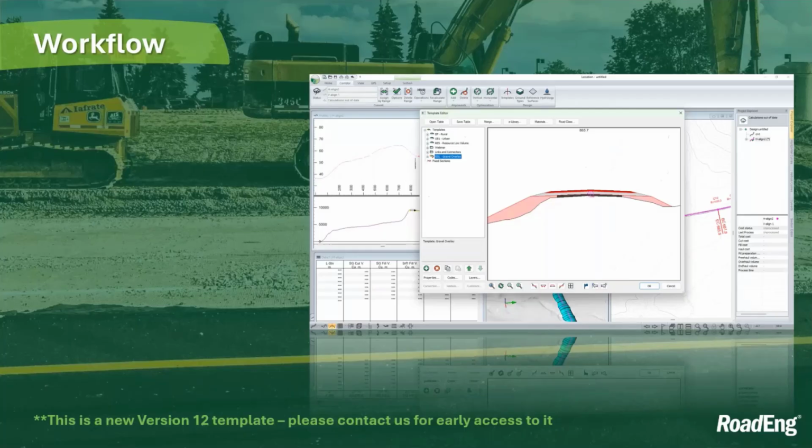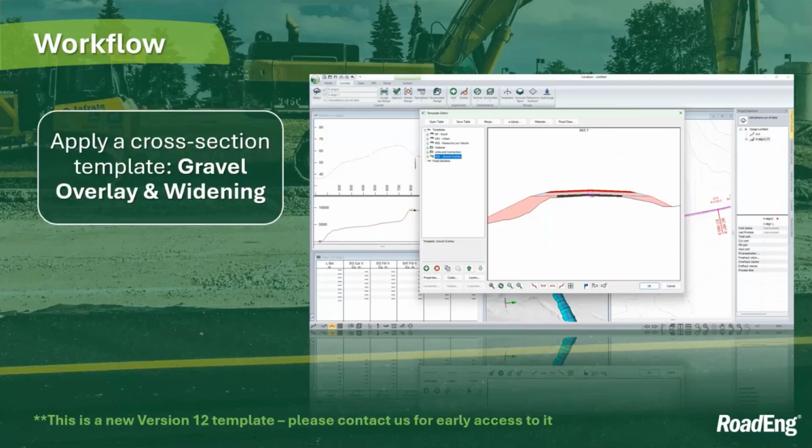We are going to be working with a gravel overlay and widening template. We're going to configure this template to reference those surveyed road edges and to have better ditching and cut and fill slopes. So a really cool template. We're going to step through that today. Again, if you go to find this one and see if it's available in your version 11, it's not. It's because it's a beta template coming with 12. But again, you can contact us for early access.